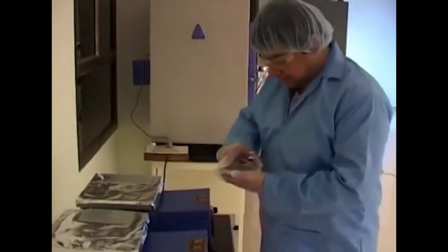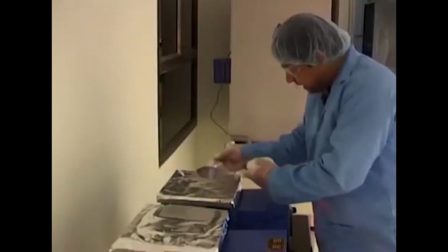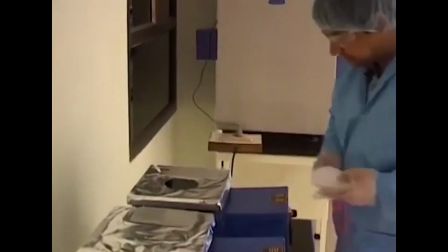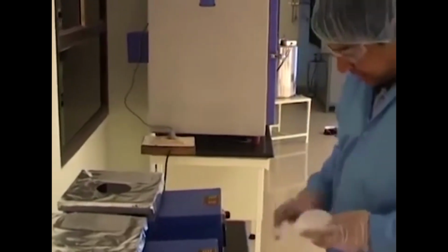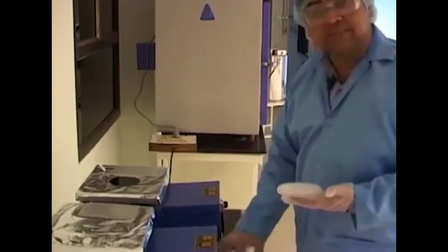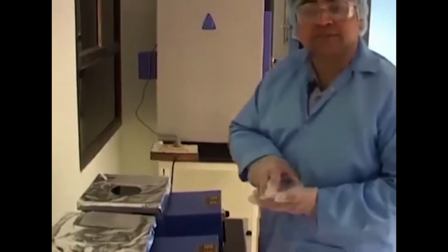So after picking it from its location, we put it over this plate which has been set to a temperature of 95 degrees Celsius. We start the stopwatch and set it to about 6 minutes. So the idea is that after 6 minutes, as we hear the second alarm, we should be able to pick this up and then again let it equilibrate back to room temperature before the exposure process.